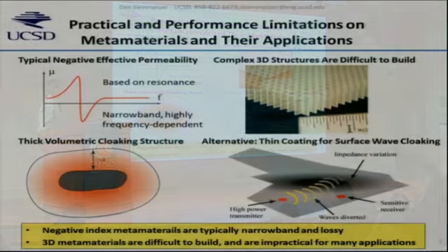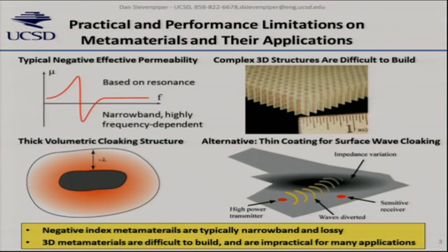Well, many of you are familiar with this concept of metamaterials. Of course, that's a new term for the current evolution of a field that's been around for a long time. In the old days, we called them artificial dielectrics. We could make permittivities that we couldn't otherwise achieve by building metal particles into a dielectric matrix, for example. Now we can also play with the permeability. So we can make effective media that have effective mu or effective epsilon that's almost anything we want, including high values, even negative values, or near zero values.